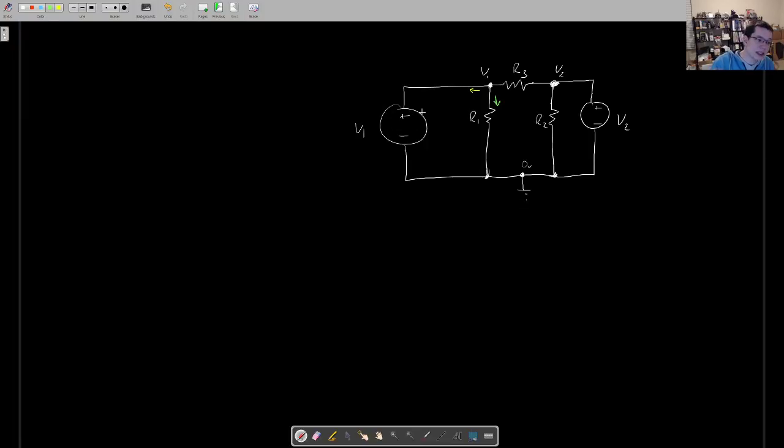Because if this has a resistance, then this resistance in parallel with the rest of your circuit is going to bring down the total impedance, which is bad if you want maximum power transfer. If you have a current source, which we haven't talked about yet, you replace it with a short circuit, which is 0 ohms, because the more resistance you have in series, the less power you're able to deliver.